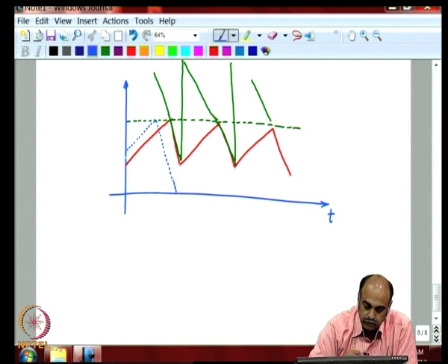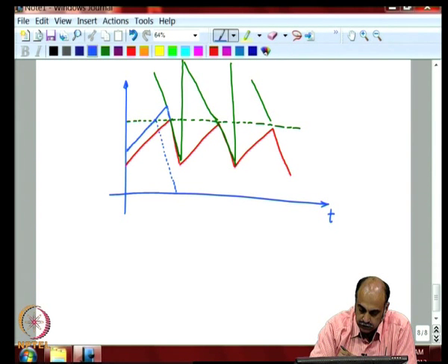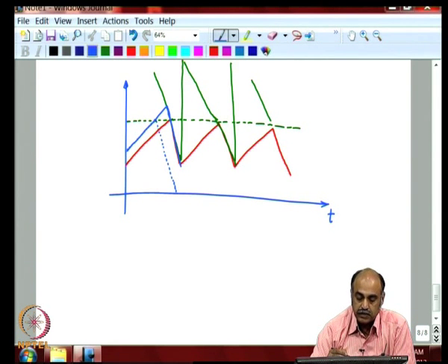So, what would happen? This would go up to this point, the inductor current compares with the reference, switches off, and then the inductor current and the reference both are coming together like that. And in one cycle, you see that the correction is happening and the error due to any perturbation at the beginning of the cycle becomes 0.